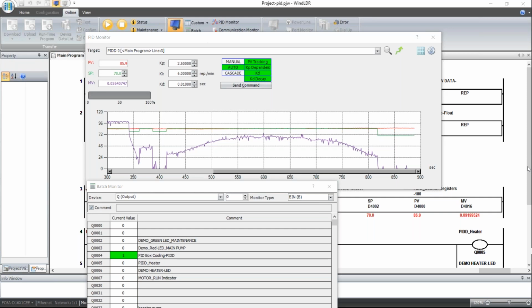Are there any limitations, like instruction limitations, for the analog output card versus the PID module? Is auto-tuning the only difference? The second question is whether there are limitations, like the 32 PID instruction limit. There are 32 PID instructions for the analog output. Your PV may be coming from a Modbus signal or something. The limitation is the 32 PID algorithms.